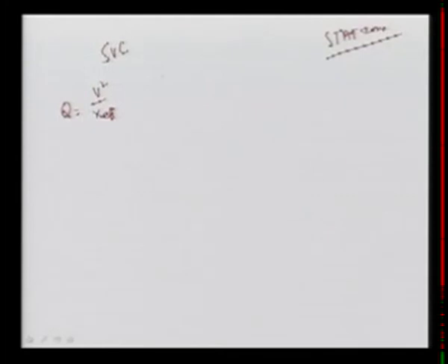Now you can see if your voltage falls down from 1 per unit to, let's suppose, 0.8 per unit. When it was 1 per unit, it was giving the reactive power at 1 per unit, it is 1 over X effective. Now at this value, this X Q will be your 0.8 square divided by X effective, and it is 0.64 upon X effective.